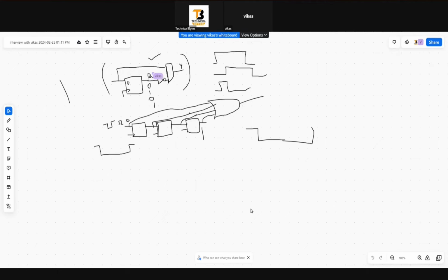Very good. But in asynchronous reset, since assertion and deassertion can happen at any clock edge, especially the deassertion of the reset can lead to metastability. That is the disadvantage of asynchronous reset. But the advantage is we can reset the flops immediately, without even a clock. But why do we want to make it independent of the clock?